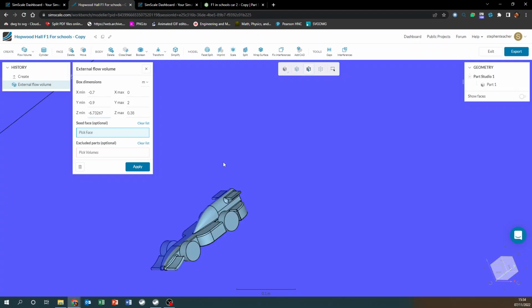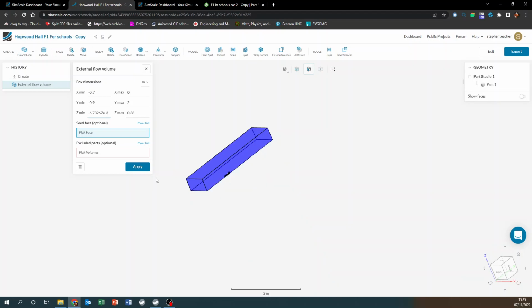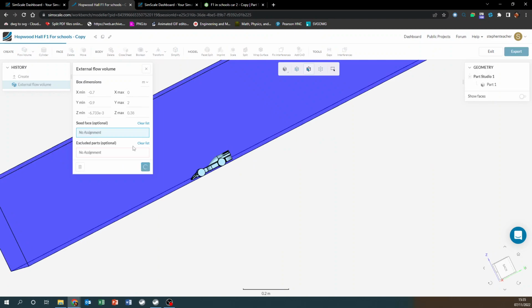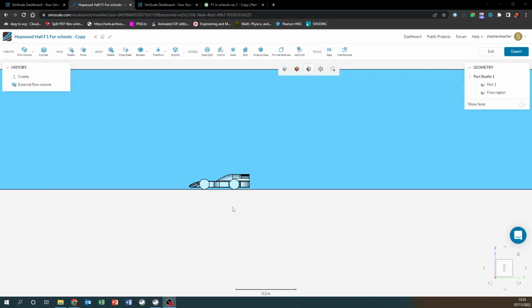As you can see, that is absolutely huge because it's wanting a value in meters. So we need to put that in millimeters. So we just need to say E, which this software uses instead of times 10. So we're saying times 10 to the power minus 3. What we should see then, if we zoom in, is that we are nicely aligned on the wheels. Okay, so I'm just going to hit apply there. Okay, so you can see we're nicely lined up on the wheels there.